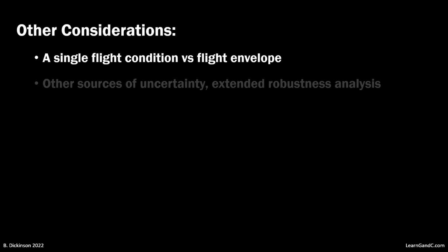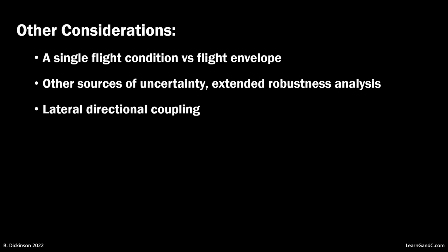A few other considerations to mention in the future. Towards readiness for actual implementation, we would need to tune controllers for an entire flight envelope versus the single point considered here. We'd also need to examine control effectiveness with coupled lateral dynamics in both linear and nonlinear simulation. And actuator rate and angle limits reduce gain and phase angle of the actuator response. Such limits would be imposed in a real system, and so they should be analyzed at this level of control tuning.